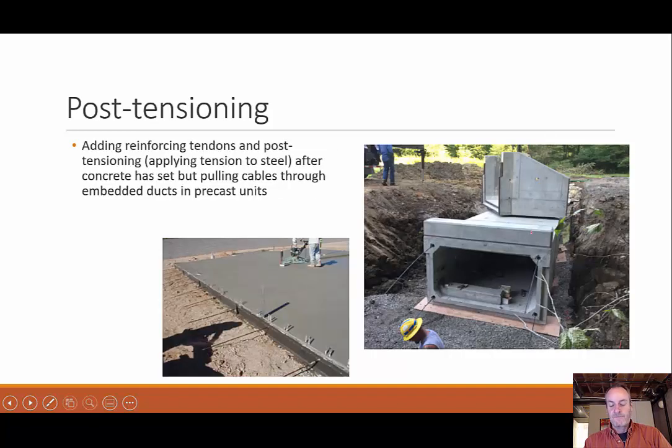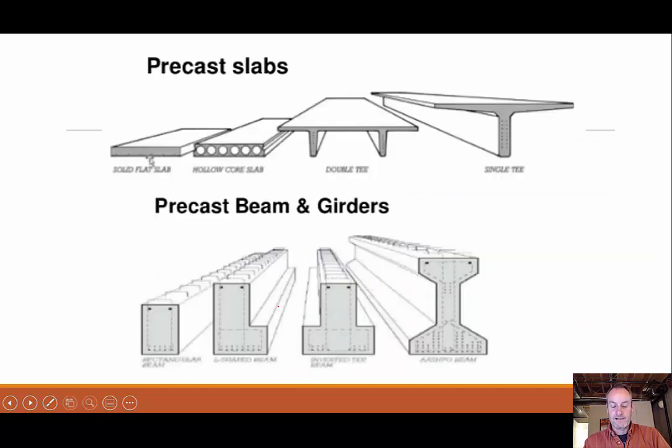It flattens out. Versus post-tensioning, you can see there's these ducts in here, right? And I have this tendon that is put through that duct that I'm pulling on, or on a slab, same idea. And I'm using like a jack to pull the whole thing close. And this is most common on like precast slabs or girders or beams, things like that.